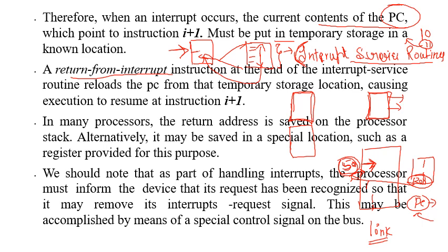So this is how an interrupt process occurs. There is not much difference between subroutines and the interrupt service routine. They are both the same, but the interrupt service routines will always have a fixed memory location. If we have a particular memory we are speaking about, then the address range to store the interrupt service routine is fixed.